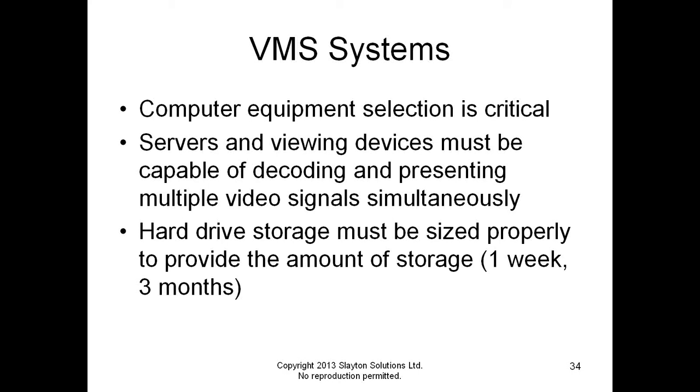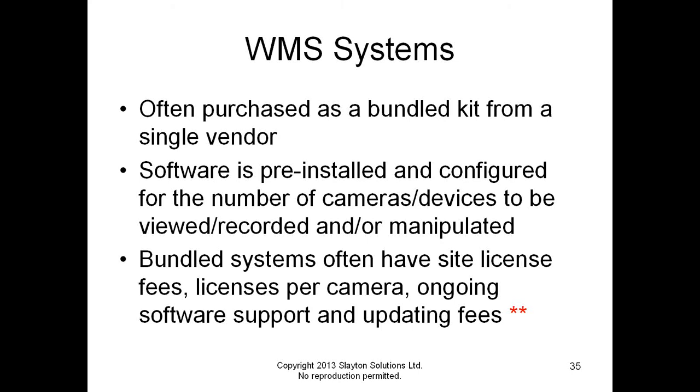of the hard drives. Now, the good news is you can buy terabyte hard drives now pretty inexpensively, but still, you've got to know how much storage you need, and all these things have to be calculated together and carefully planned so that the system will work the way the customer wants it to, and the amount of storage will be there for the customer to be able to review the video.